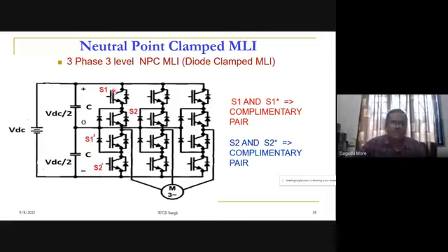So how many switching signals do we have to generate? We have to generate 6 switching signals. If we know the switching signal S1 we generate, S2 we generate for the first leg, similarly for the second leg and third leg, and correspondingly the other 6 will be just the inversion of these.